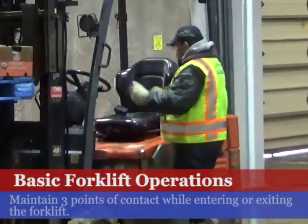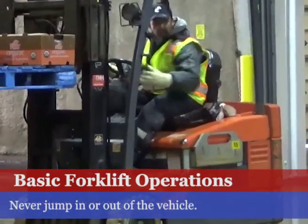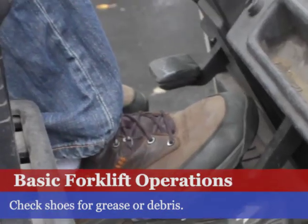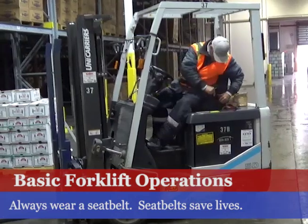When entering and exiting a forklift, maintain 3 points of contact. Never jump in or out of the vehicle. Make sure that your shoes don't have any grease or debris that may cause you to slip. Always wear your seatbelt. This can protect you from falling out of the vehicle in case of a tip over.